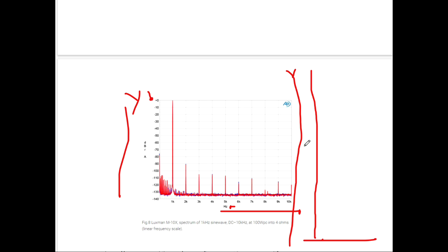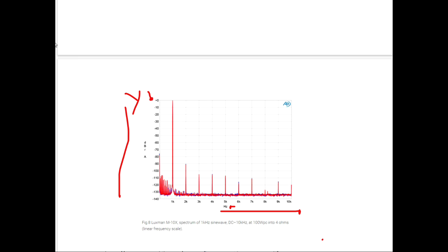Well, that's not very handy. So if I put it into decibel form instead of voltage, it's going to squeeze things down a little bit so I can get a better idea. I can look at them more visually and squeeze it all into one chart.